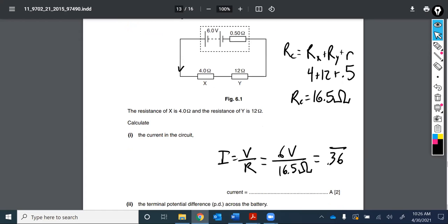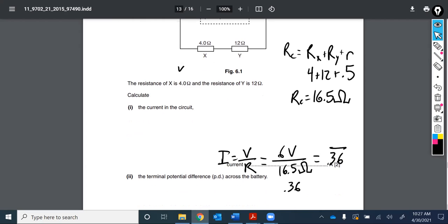And so I'd be tempted to call that just 0.36, because the 363 would round down, so we'll just round it to 2 significant digits. 0.36 amps should be the current in that circuit that you calculated. If you didn't get that answer, give yourself feedback right now. Maybe you didn't know we had to do that, or you might have got caught up with the V equals E minus IR equation. Maybe we'll need that eventually.